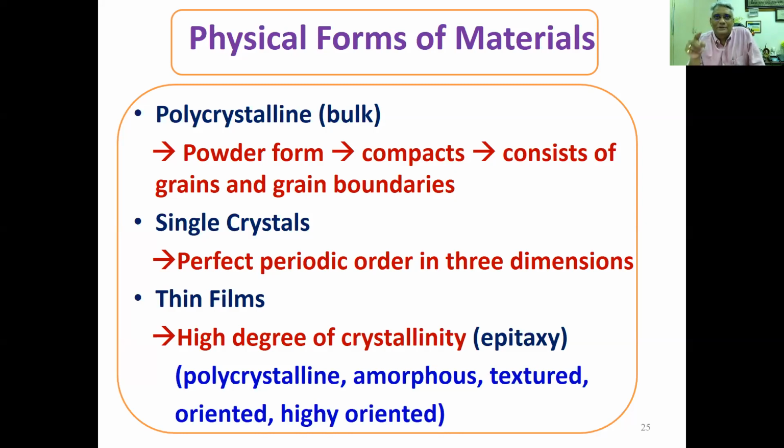But I said the same physical vapor deposition, the second method, which is sputtering, I'll go into the details of sputtering later. It requires the material in a bulk form. I said you need the material in the form of a 2 or 3 inch cylinder with, of course, very small thickness. So it's a circular disc with a small thickness. You need that. So how do you get it?